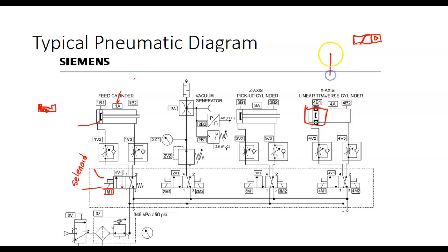Yeah, that's all it is. It's just a fixed rod, and it's got a big old hockey puck magnet in there. And then we just come up here and push that, and it causes the magnet to move down to one side, and we put it on that side and it moves back. The carriage, what's actually supporting whatever we've got on there, just clamps onto that magnet. You can actually break the carriage loose on the lift on the Festo line, and then you've got to get it recoupled, which is not easy, but we've had that happen before.